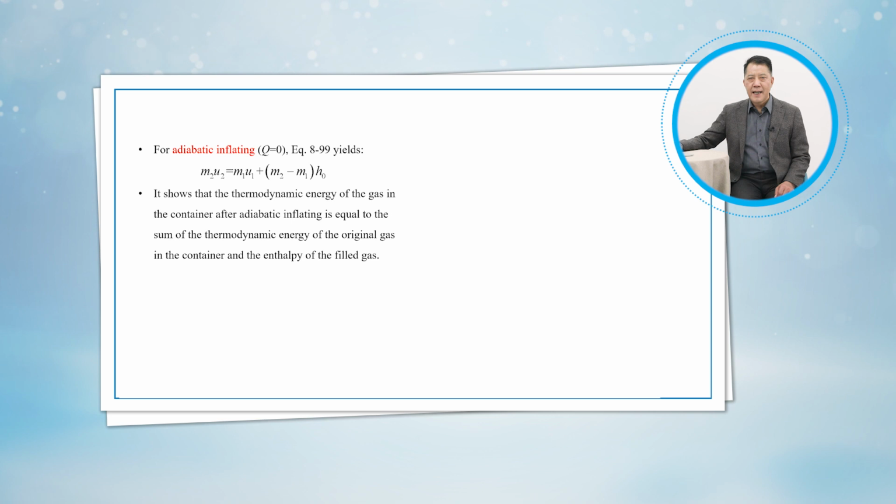Let's first talk about the fast inflating, or the adiabatic inflating. For adiabatic inflating, simplifying equation 8.99, we have this energy equation. This shows that the thermodynamic energy of the gas in the container after adiabatic inflating is equal to the sum of the thermodynamic energy of the original gas in the container and the enthalpy of the filled gas.